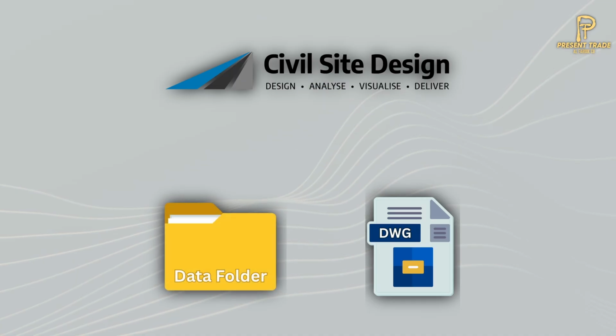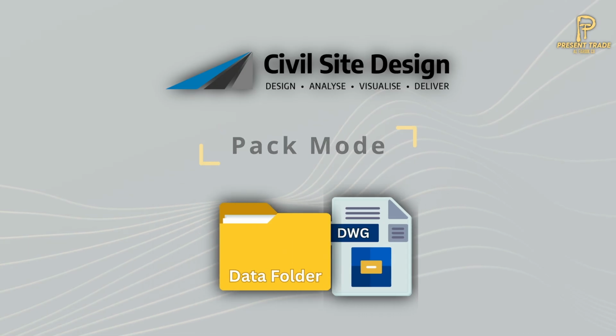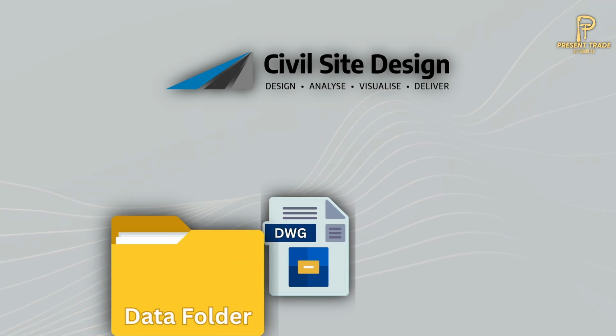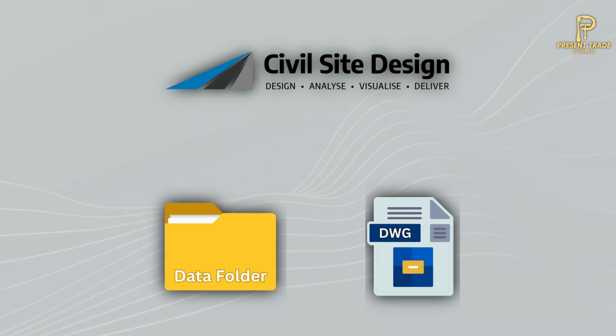In newer versions of Civil Site Design, there is another method called pack mode, where the data can be stored directly inside the DWG file, and we'll discuss that in another video. But for now, let's focus on how the Data folder works in practice.